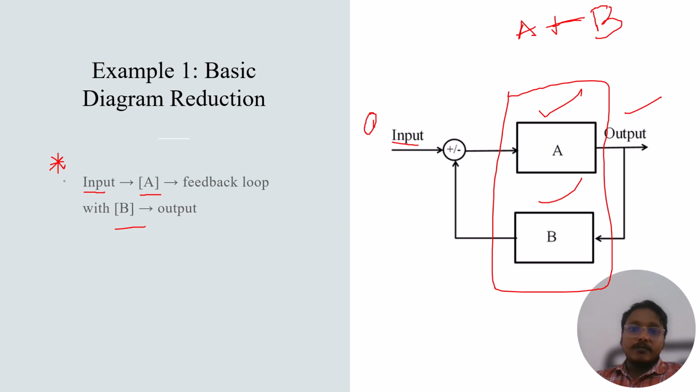And this is the feedback loop. Then I need to see whether it is a plus or minus, and according to that we need to decide. So 1 by, as it is a feedback loop normally, right? If it is only these two blocks, then I can write it as only this. But what is going in is added in one summation block. So that means it is a feedback loop. Whenever the feedback loop is there, this feedback B will become part of the denominator. So that means A by 1 plus AB.